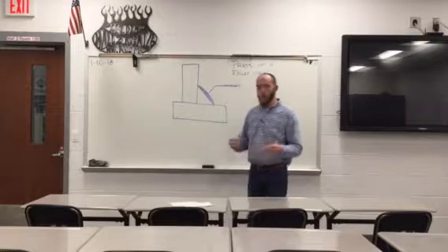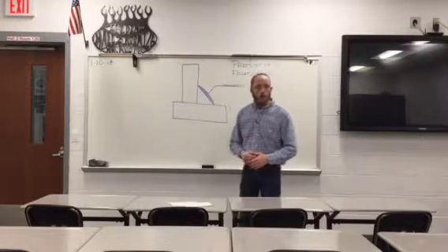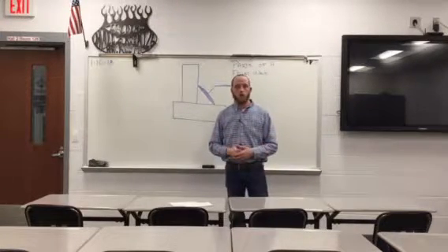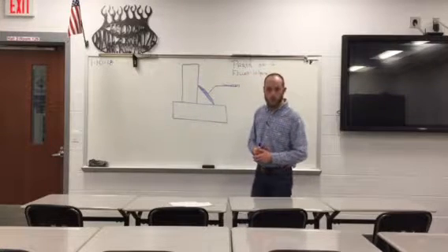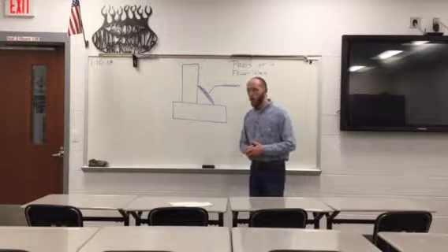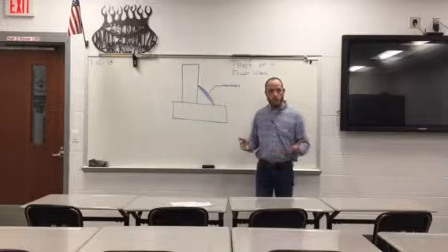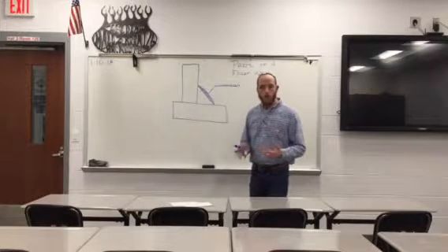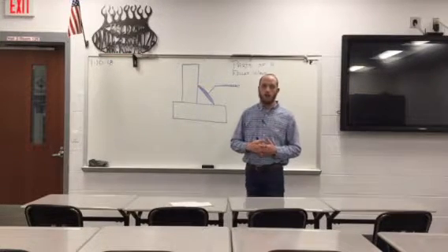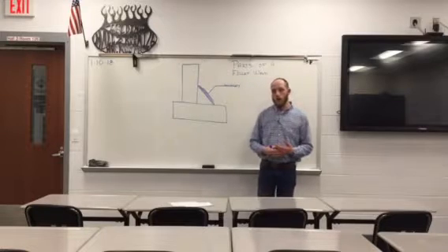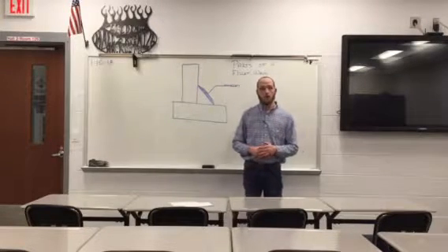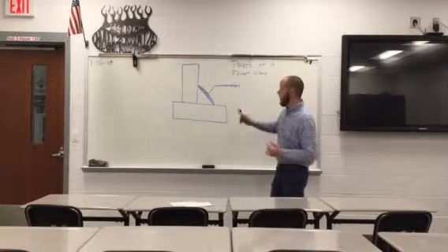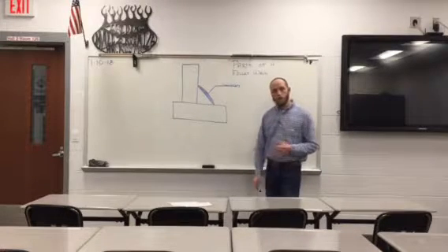Now, let's say we have more than 1/8 of an inch of weld convexity. Certain circumstances will call for you to grind that excessive weld convexity down. Or in critical testing, if you have more than 1/8 of an inch, you'll fail that test and either have to retake the test or, in the worst case scenario, lose your job over it. So, weld convexity is a very important term for you to remember.